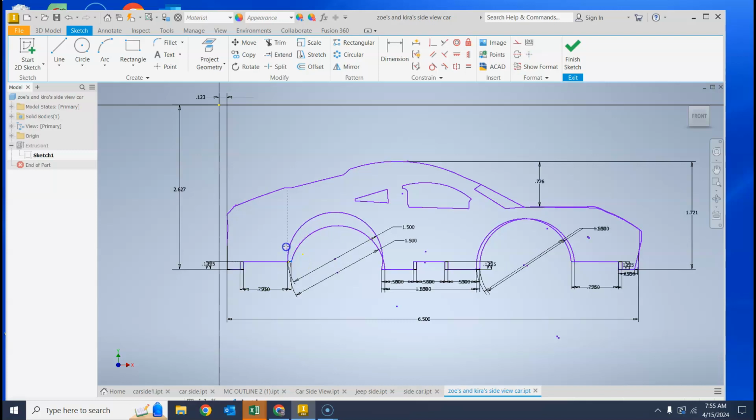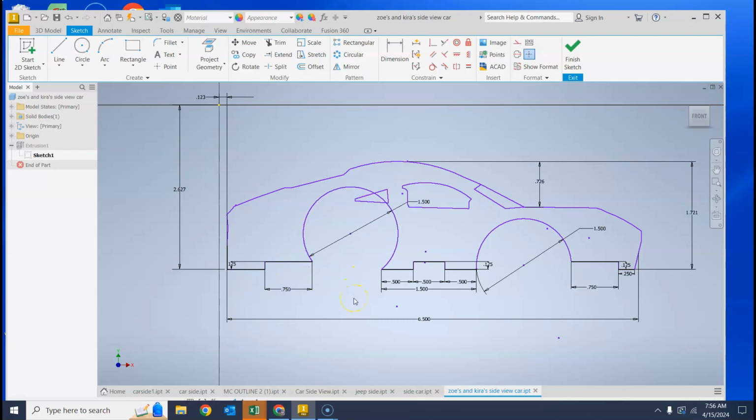I'm going to try to drag this one point, and notice that changes the location of the wheel. Okay, so I'm going to try to figure out why that wheel is blue. So what am I changing right here? I'm changing the size of the wheel. Looks like this dimension right here keeps getting bigger and bigger and bigger. So this dimension was never set. Okay, so I need to set a dimension from here to here.